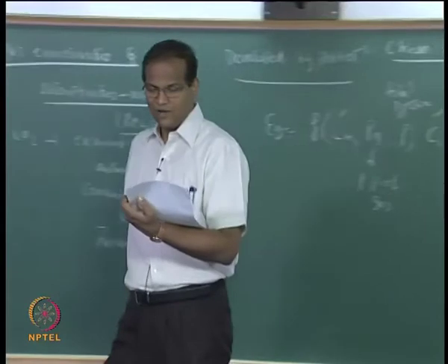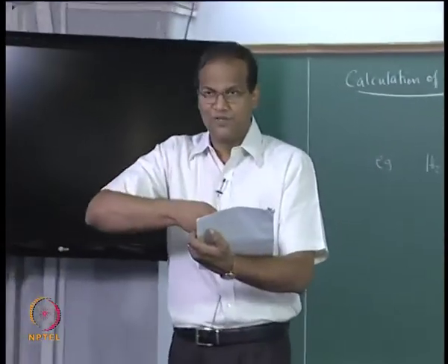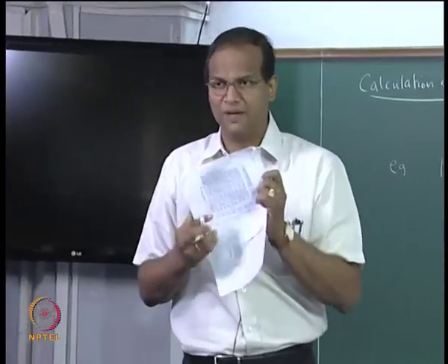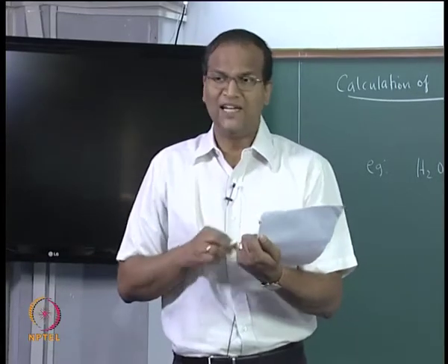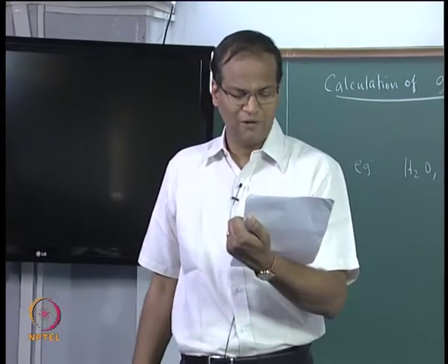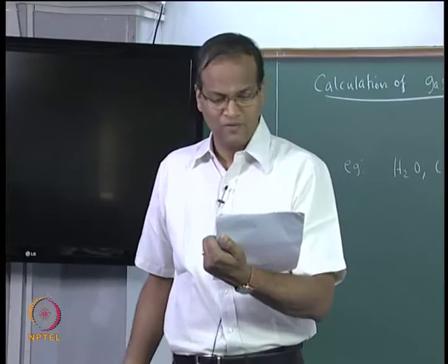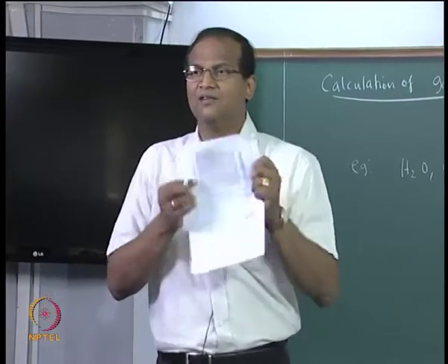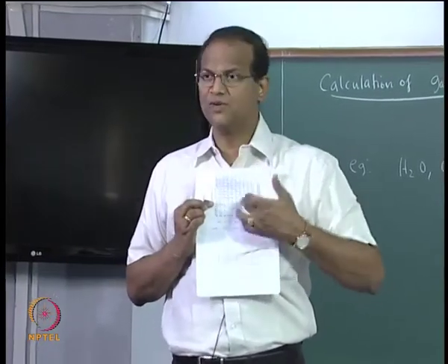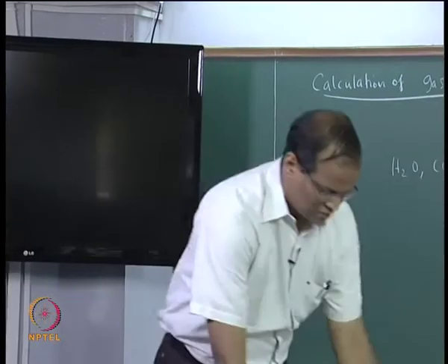Okay, now various curves are available for various values of this parameter, and Tg is the gas temperature, given in both Kelvin and Rankine. Based on these two you will straight away read the value of epsilon c. Okay.